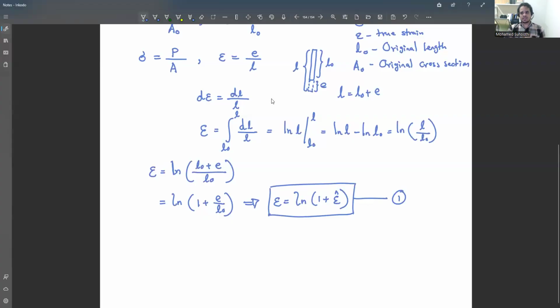This is very important because to find the relationship between nominal stress and true stress, we take one assumption. You must be very careful and understand this assumption, because I have seen many papers in finite element, even at the researcher level. If someone uses Abaqus or ANSYS, in Abaqus, for finite element software, we use true stress and true strain for the material model. If you run an experimental study and want to define the material property as a stress-strain relationship in Abaqus, you have to define true stress and true strain.